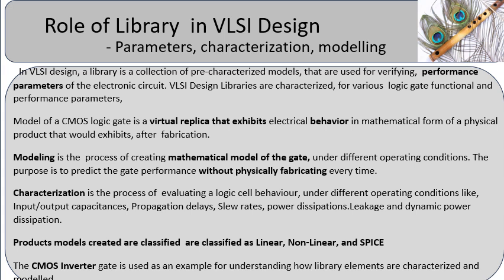Characterization is the process of measuring or simulating the gate's behavior under various operating conditions. These results are stored in library formats and are used for simulation and verification purposes. In this video, we use the basic CMOS logic gate, the inverter, to demonstrate modeling and characterization of logic gates.